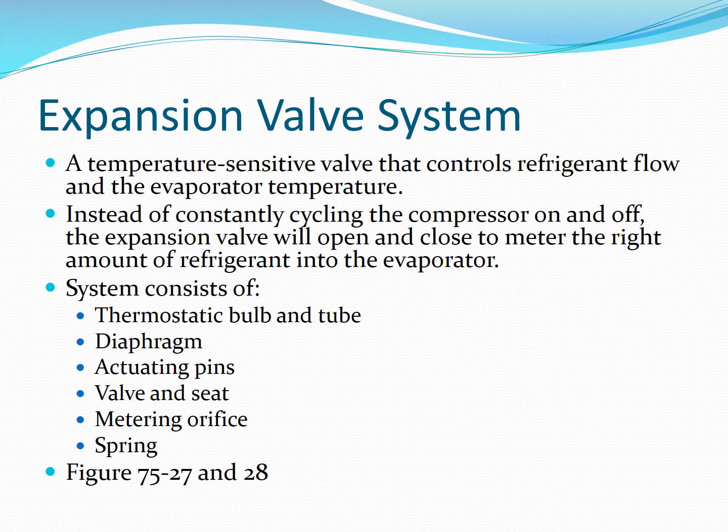On the expansion valve system, I had mentioned much earlier to think of a thermostat in a cooling system. Most of you have seen that thermostat come out of a cooling system, and you know how it operates: it can open and close. It's going to control the flow of coolant through the system, and it's closed when we start up the engine, and then as the engine warms up, it starts to open, allowing coolant to flow through the radiator. Well, this is essentially the same thing on the refrigerant side. This is a temperature sensitive valve that controls the refrigerant flow based on the evaporator temperature.